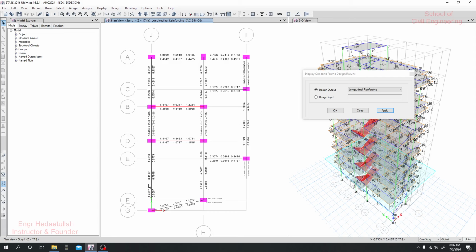So if I provide that reinforcement of 1.42 inches square here also, then it will be almost double. And see, for that beam it requires 0.86 maximum, 0.57 maximum, 0.7777 maximum. So if we provide the same reinforcement for that beam, I think it will be more and more uneconomical.